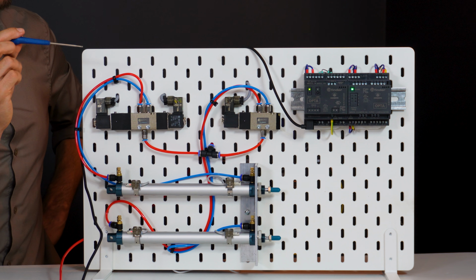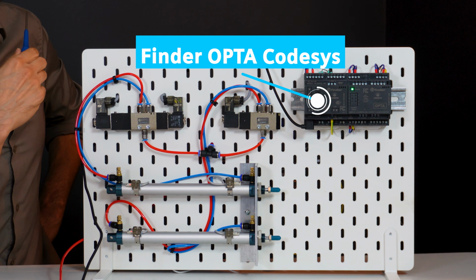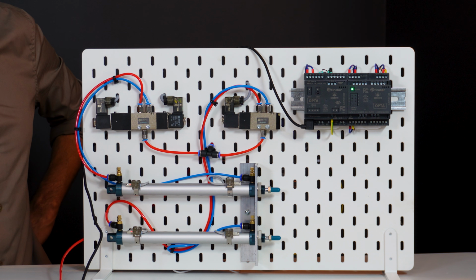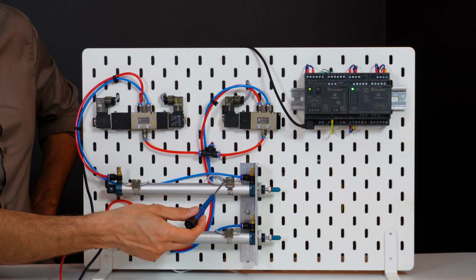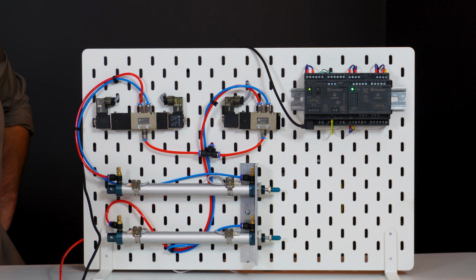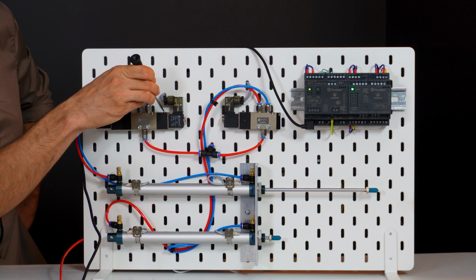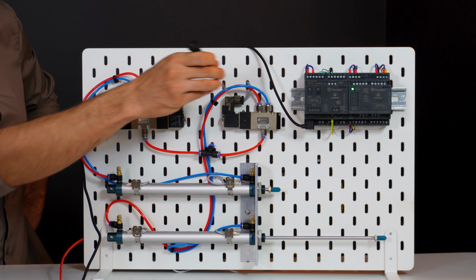The brain of our system will be the Finder OPTA controller on Codesys. This controller is equipped with Codesys runtime, and we can use the Codesys environment to program this controller. The task of this controller will be to read signals from the limit sensors of the base position and the working extended position. Additionally, the controller will power the coils, triggering operation for the actuator with a 3-position distributor and for the actuator with a 2-position distributor.